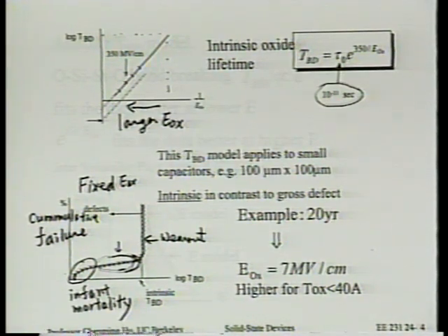But usually people consider a constant voltage stress the more appropriate model, right? Until you get very close to the final portion of the lifetime of that weak spot. Maybe that final time is only milliseconds long. At that point, it's so leaky that indeed it sinks all the current that you have to stress it. But in terms of the stress time, that's a very small portion of the stress time. Whereas for the majority of the stress time, the entire oxide is stressed by that field. Okay? Right. Other questions? Excellent questions, all right?